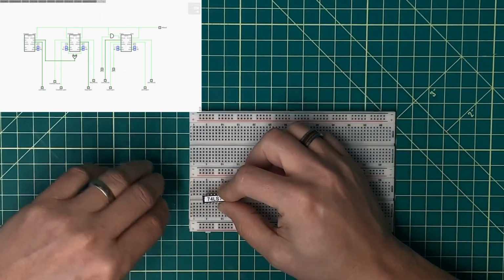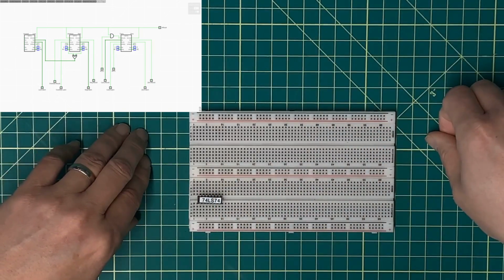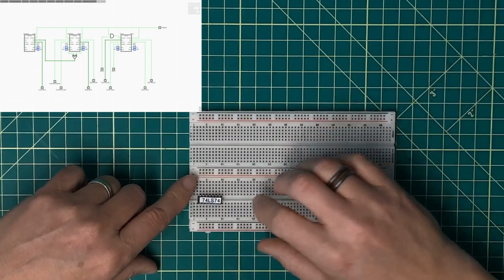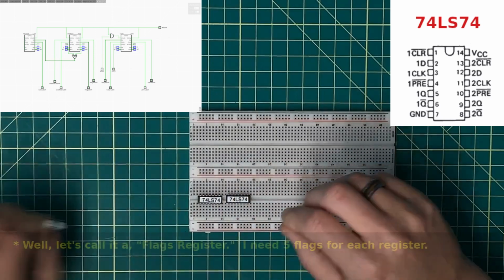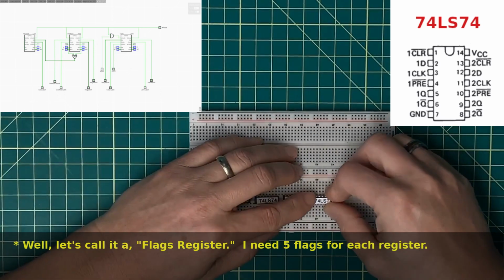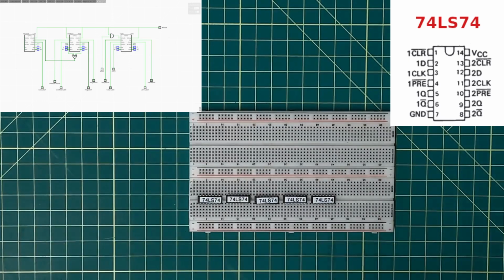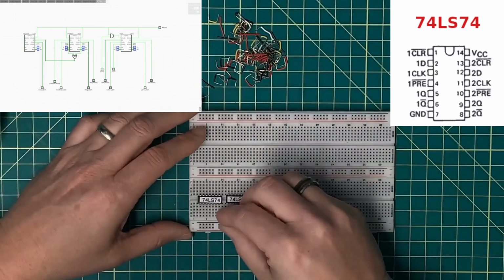This is a 74LS74 IC. This is again that dual D-type flip-flop. So there's one on the bottom and one across the top, and I'll stick a pin diagram up there. And I need 5 of them for each flag, but I also need to build 2 of these. So in building 2, what I need is one for the program flags and one for the interrupt flags. And that should give me what I need in order to maintain state when I'm changing from interrupts to program mode and back to interrupts.